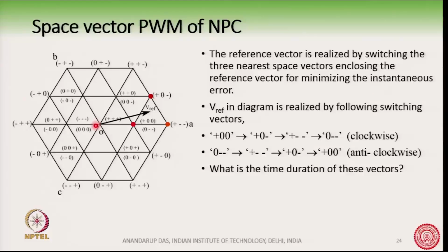Suppose my reference vector is here, I will switch the three space vectors which are nearest to this Vref and enclosing the tip of Vref.